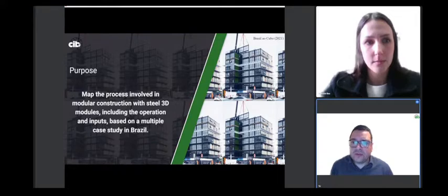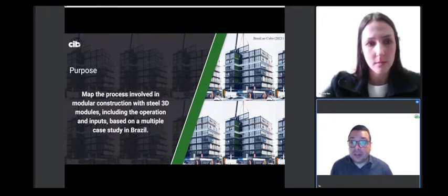Talking about what we found in literature, modular construction has some phases. This comprises design, pre-construction, construction, and post-construction. The first phase includes design and permissions. Pre-construction comprises the planning and scheduling of activities, engineering, production of the modules, site preparation, and also foundations. The construction phase includes stages associated with managing the delivery, transport, lifting, on-site assembly of the modules and their installation, where modules are connected and finished with adjacent units. Finally, the post-construction phase includes occupation, monitoring, and possible reconfiguration.